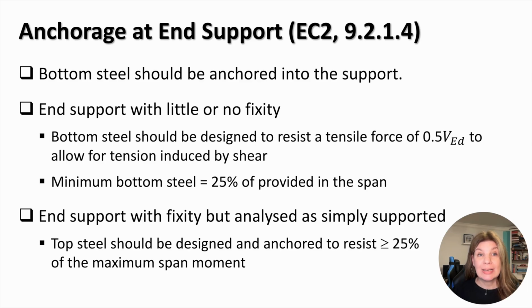For end supports with little or no fixity, bottom reinforcement should be designed to resist a tensile force of 0.5 VED to allow for tension induced by shear, and the minimum bottom steel should be equal to 25% of that provided in the span. For end supports with fixity but analysed as simply supported, top reinforcement should be designed and anchored to resist at least 25% of the maximum span moment.